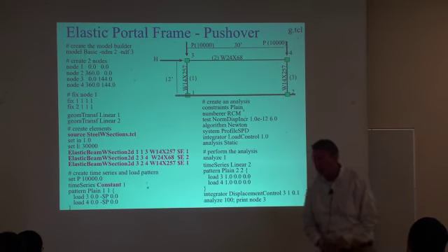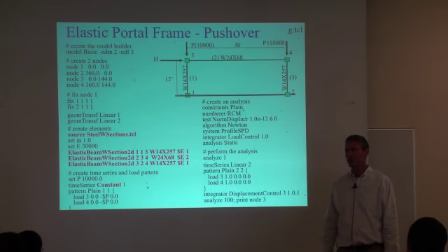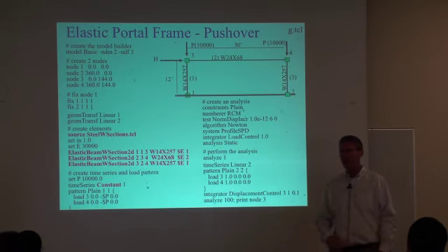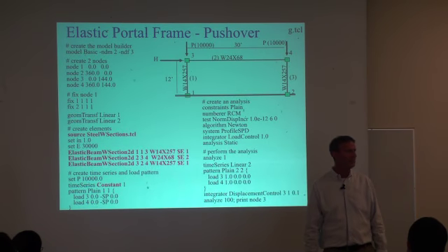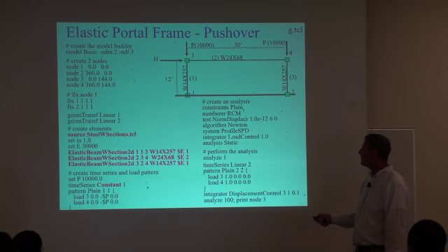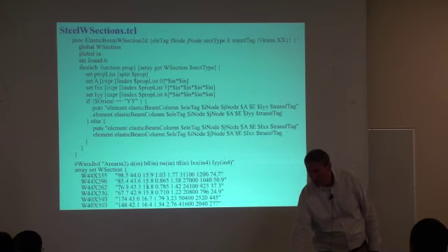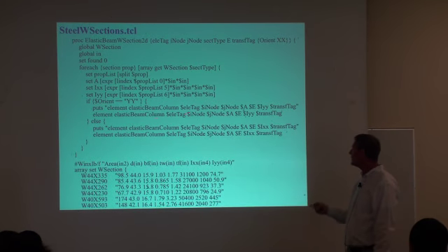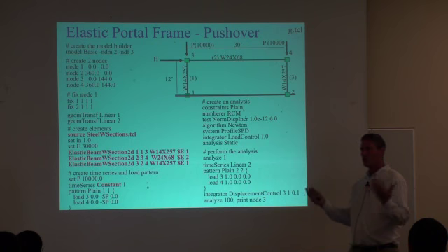If you're doing a lot of steel analysis, you can have a nonlinear beam, W section 2D, which would automatically go get your things through your fiber discretization, create your materials for you. So you can be clever about how you do things. Use the power of this programming language to make your life a lot easier. And when you're looking at your script later on, this is a lot easier to figure out what this model was, rather than having A, E, I, and those values themselves. As I say, I could have just issued these commands here with the different A, E, and I's in this previous script. But this just looks a lot more, to me reading it, I can see exactly what the model was. Okay?